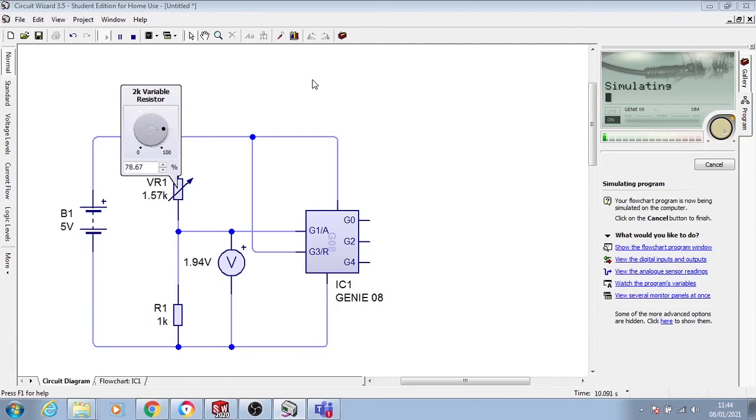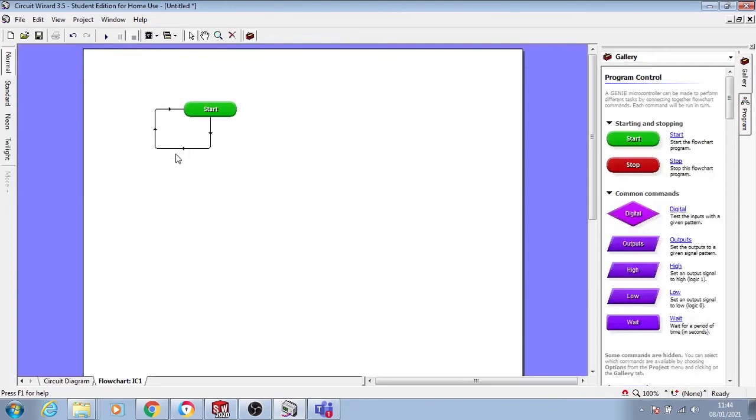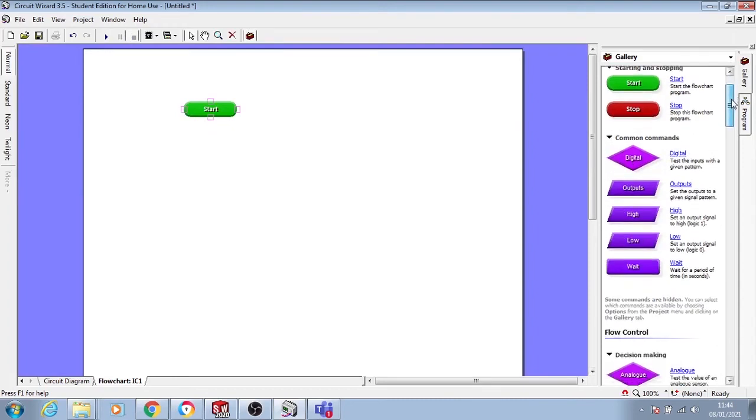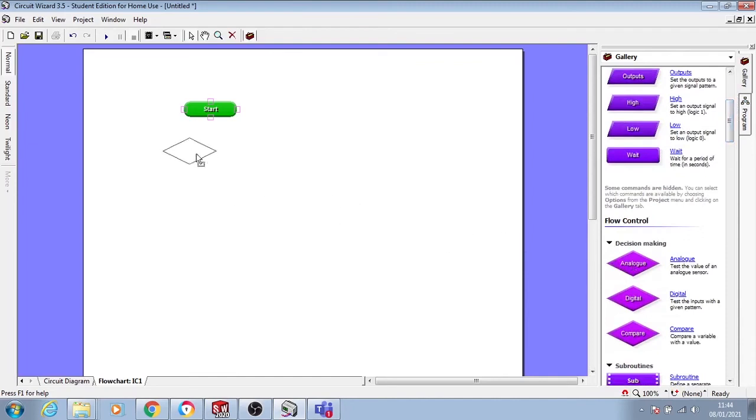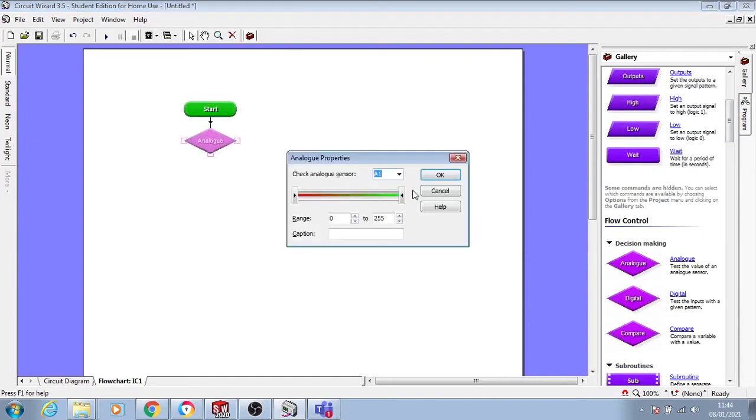Okay, so a really basic introduction to how to control a sensor, one of many different types of sensors, into a PIC chip. Now if you were going back to the flowchart, instead of looking at a digital input read, we look at the analog input read here. Now what's happening in the chip, instead of saying check the voltage, is something called an analog to digital conversion, ADC.